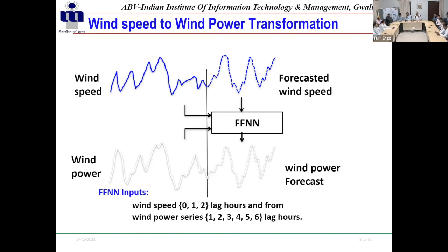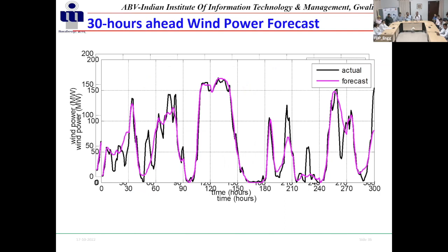This estimator is giving the best output result. You can see how it is matching. Actual and forecast are very close. Only the spikes, I just said, are very difficult; no estimator can pick them up because they are outliers. Outliers means suddenly the wind speed has increased and the output has increased. But actually, it is following the trends, and that error is not very high and is basically manageable. This is only on the higher side, not the lower side. On the lower side, a very small value is also there, and that is giving the error.